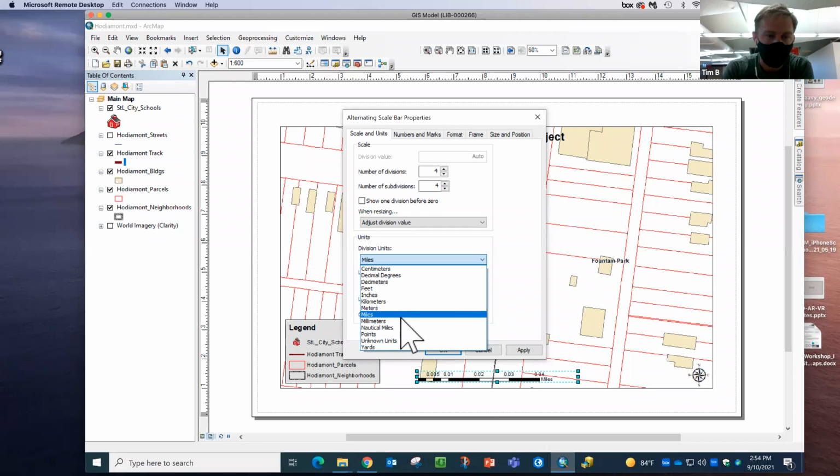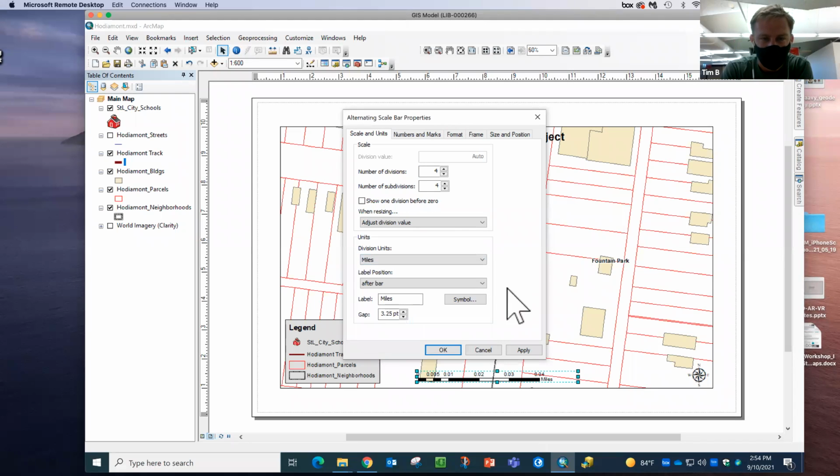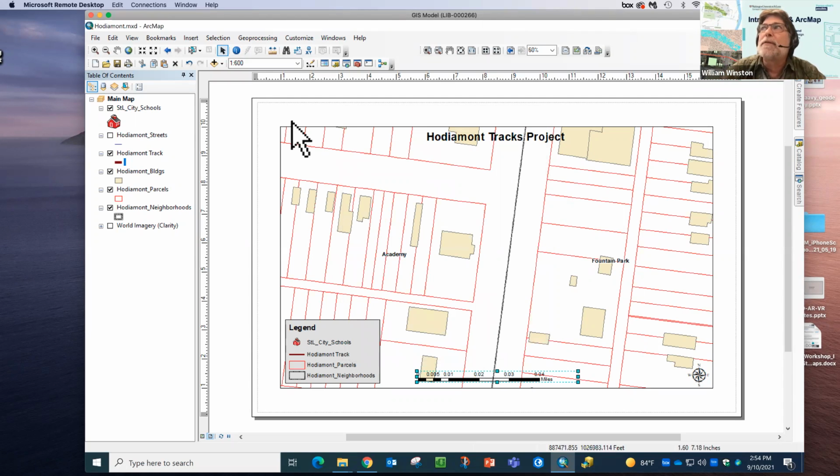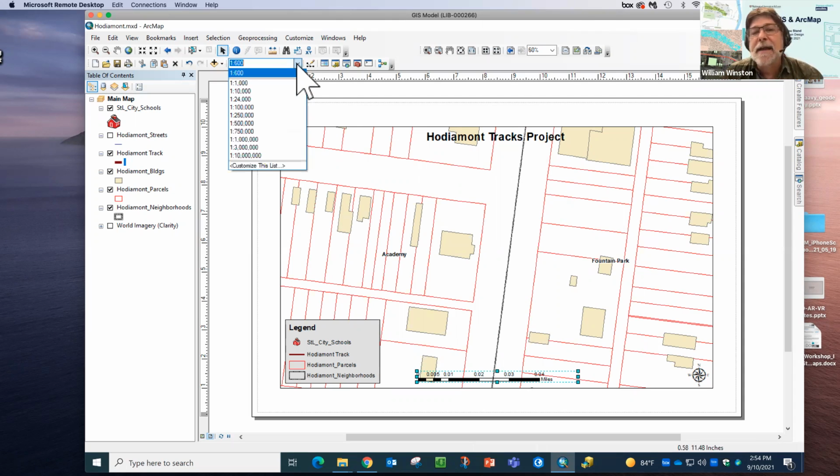What was that conversion that you just did though? How did you get 600? Well, the scale represented by this drop down menu up here is a unitless scale. You were talking about, well, you didn't mention a scale, I did. 1 inch equals 50 feet. And so you would need to make the units match between those two to basically take them out of the equation. So in 50 feet, how many inches are there? It's 12 inches to a foot. So you do the math, and you end up with 1:600.